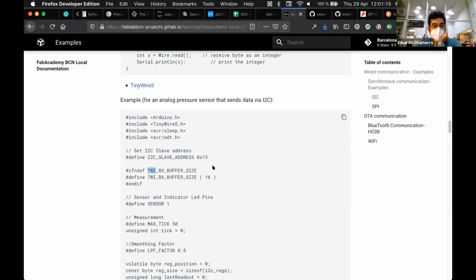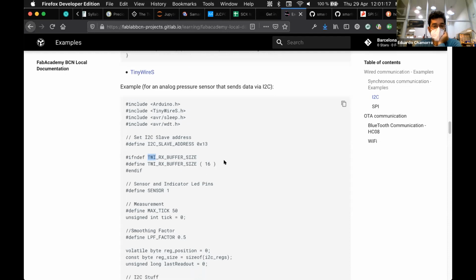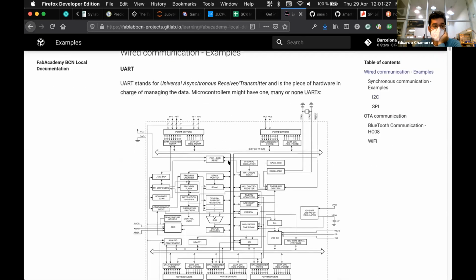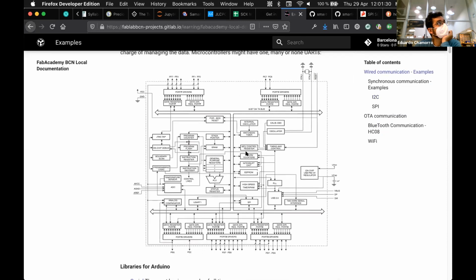Basically here, you define it by software. It doesn't have an I2C bus, the functional diagram doesn't show one, and you just do it on the pins, in software, in the process that we call bit-banging, which is basically sending bits very fast, high and low, and by that we simulate I2C.